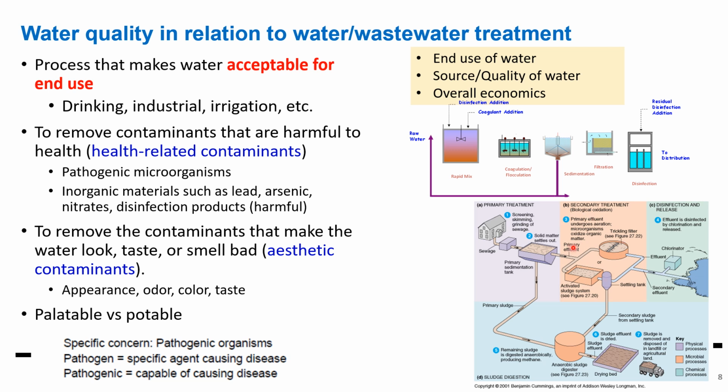So now we are doing this biological treatment because of the existence of biological BODs. And then we go for disinfection as well, and then it depends on what kind of use will follow. If it's for drinking purposes, for example, probably there will be further reverse osmosis at the end in order to make the water quality acceptable for end use.